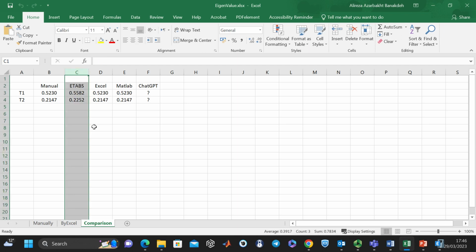It means that a finite element model always gives you larger values for the natural period of vibration than the manual calculation or even the formulas in the Eurocode, which is somewhat like a manual calculation. If you remember from previous lectures, we had a simple formula in Eurocode 8 representing the first mode of vibration of the structure, to be used for seismic loading.